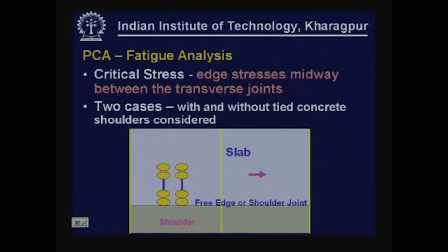For fatigue analysis, the critical stress, because if the load is placed in different regions of the slab, the tensile stresses that will be developed will be different. So, the critical condition of load position has to be selected. The critical stress condition is considered to be the edge stresses midway between the transverse joints.